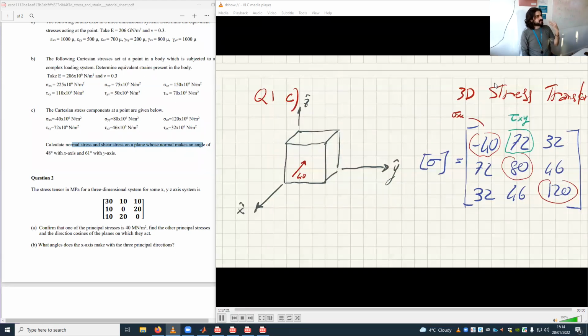So this is the shear stress that lives in face x, in direction y, which is this direction here. It's a positive 72, so it goes in direction y, and it's 72. And of course, there must be another one that goes like this. And this one is tau yx. Do you agree with me? This is this and this. 72, 72. They must be the same.